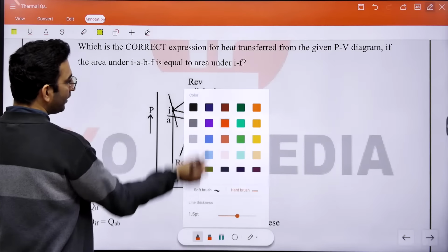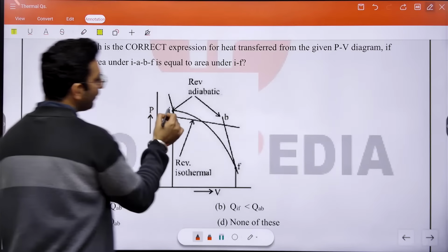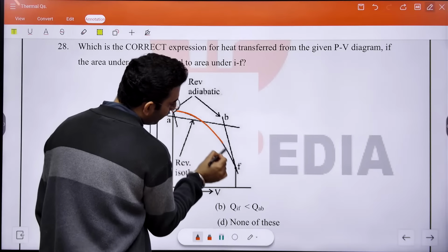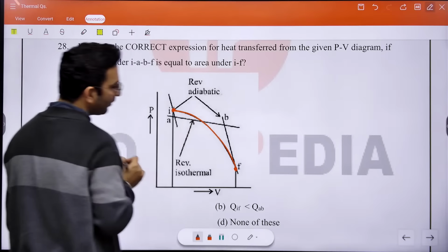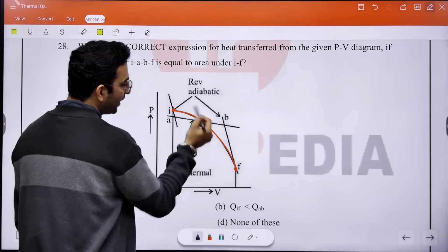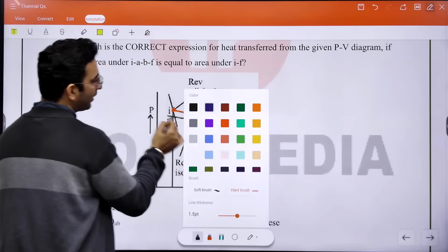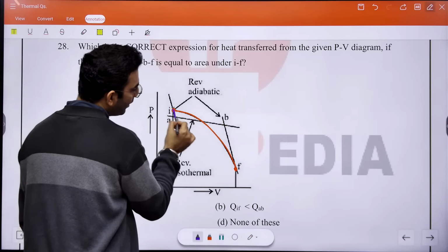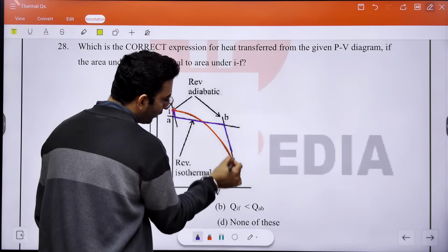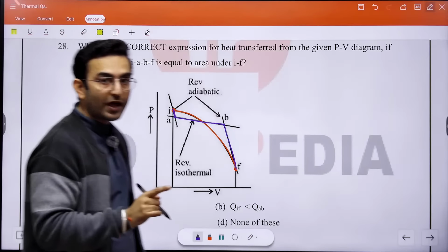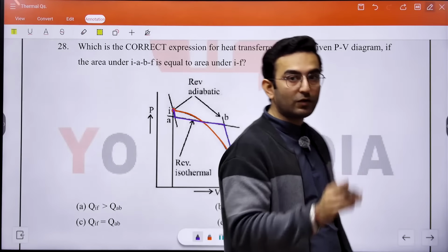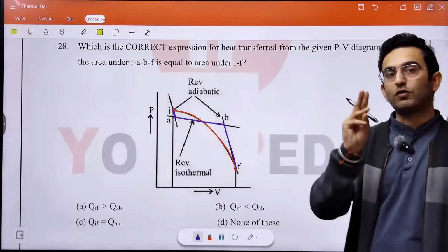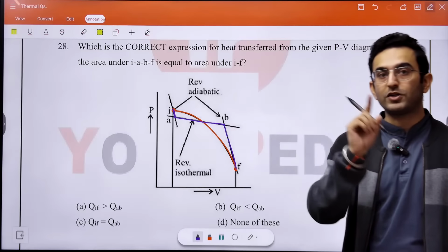from here we derive the Clausius inequality. Here we have some initial point, and we are carrying out a process I to F. This is our first process. Now this process is being converted into three different processes. We perform the first process I to A, then A to B, and then B to F. Remember that in thermodynamics, every reversible process can be written as the sum of three processes, out of which two are reversible adiabatic and one is isothermal.